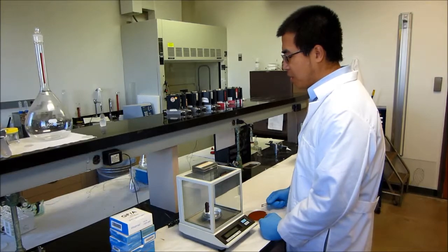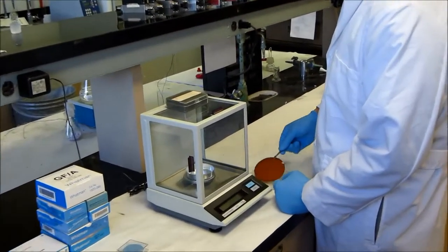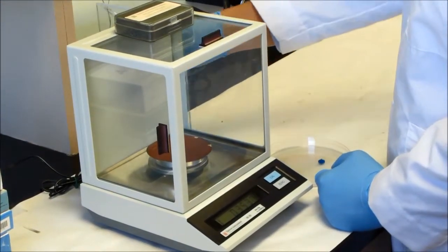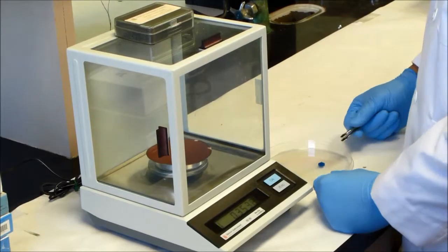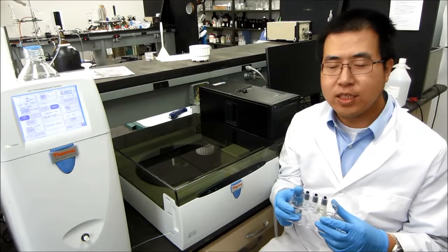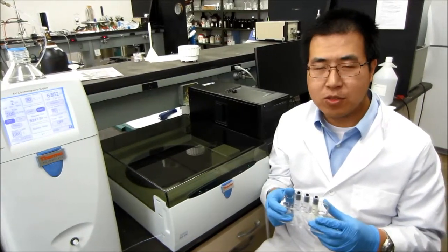The amount of fume collected on the filters will be determined gravimetrically. Each filter will be weighed 3 times. Total fume generation rate will be calculated by dividing the fume mass by arc time. After weighing, each filter will be cut into halves. Each half will be subject to a different extraction method.